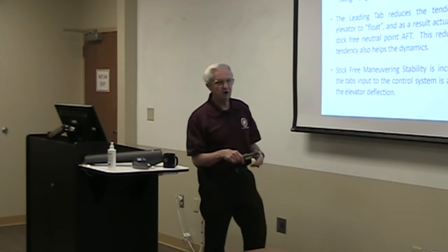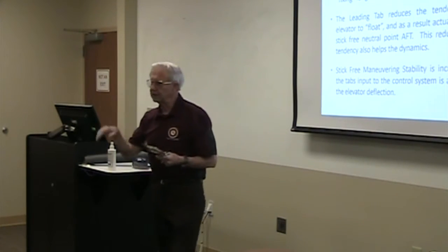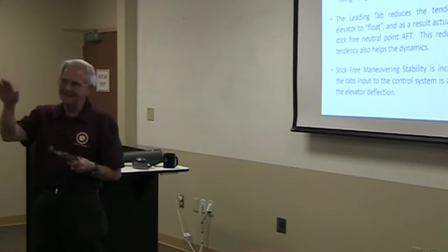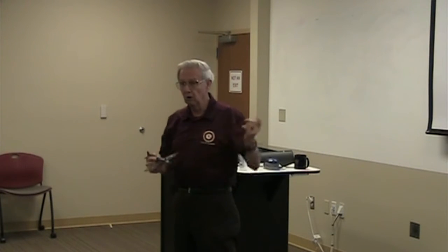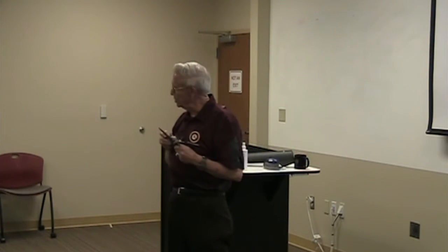the floating tendency. It also helps the dynamics, because what's going on in the phugoid is that the elevator is floating. As you slow down and speed up, it floats back and forth, okay? So this thing tends to make it want to stay where it was.